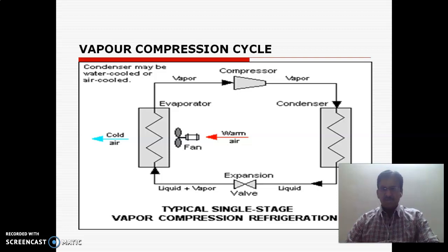So if you see the applications of evaporative cooler and water cooler, the basic difference is that we are using the vapor compression cycle in a water cooler, while in an evaporative cooler there is no refrigeration cycle, no refrigeration unit. In an evaporative cooler we use only a blower and a small pump for distributing the water into the pad, and the hot air coming in is passed through this pad, and it becomes cool by taking moisture from the water distributed on the pad, and this cold, moist air is then circulated where we require the cooling effect or cold air.